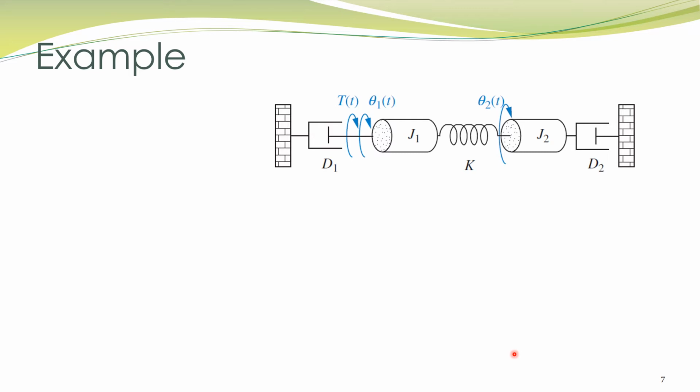That is, first of all, we identify the number of linearly independent displacements. Then we sketch free body diagrams. Once we have free body diagrams, we can write the torque balance equations to obtain a mathematical model.